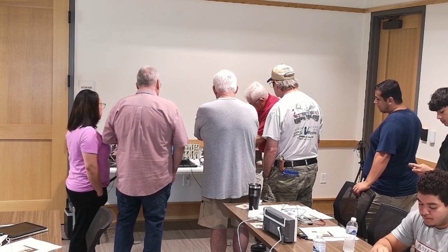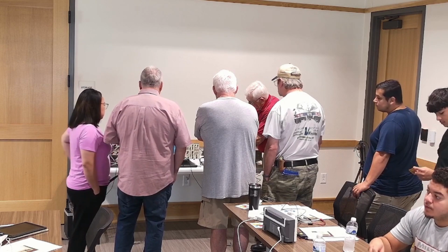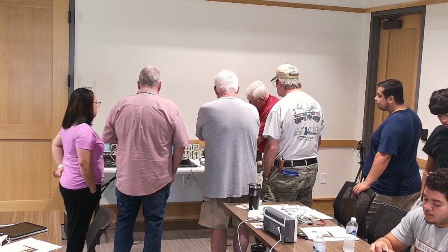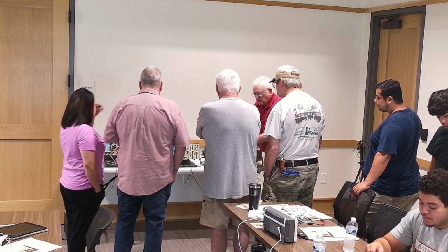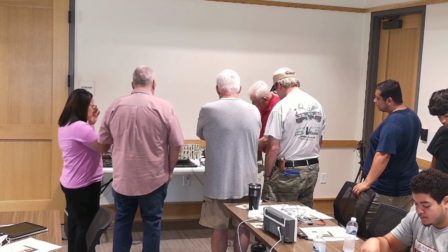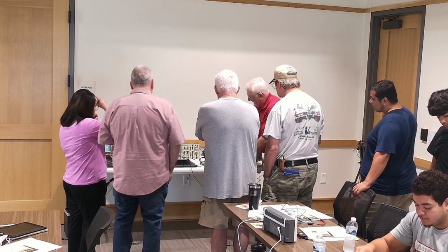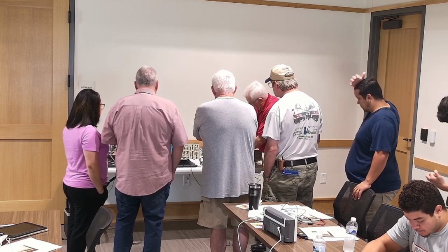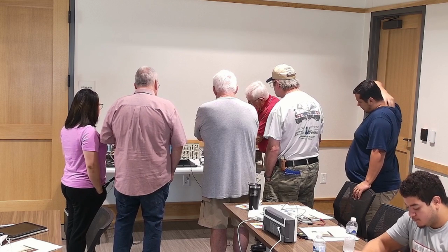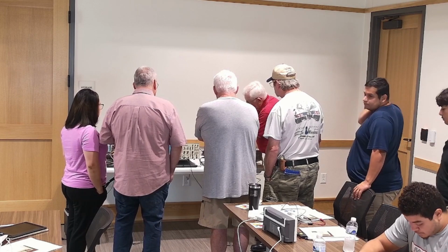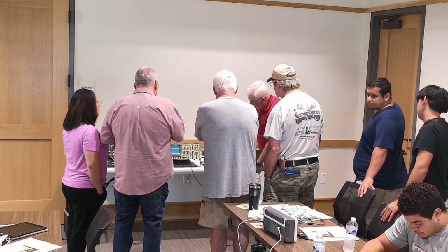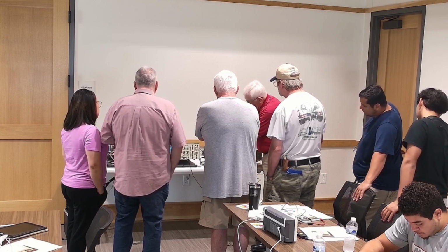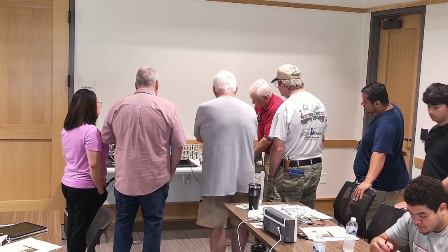And likewise, you can do the same thing with the scale. You can change the time base to spread it out or shrink it down to make it easy to read. If it's like that, that's kind of hard to read. We'll pull it up there a little bit more like that. Then I can say go from there to there, and I can measure that much easier. Of course, on this scope, it's telling you what the frequency is, so that's kind of nice.